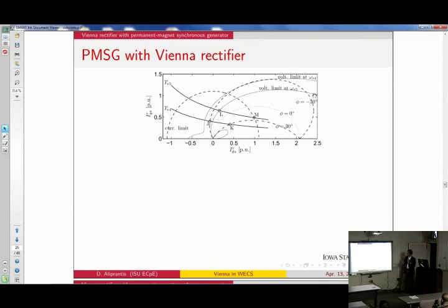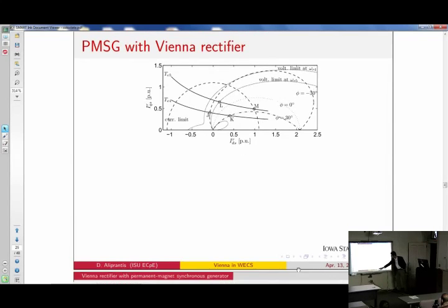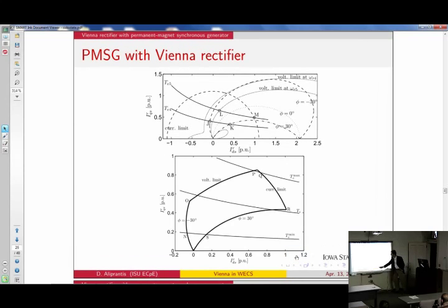So you need to draw all these curves carefully on the plane and do the same process again. For whatever torque you need to generate, you find the limiting points. For example, for this one, you are limited out here by the voltage limit, and here by the angle limit. As you keep increasing the wind speed, you look carefully at your limits, and you come up with another feasible operating region, which has a different shape this time than before. If you are inside this region, you are okay.